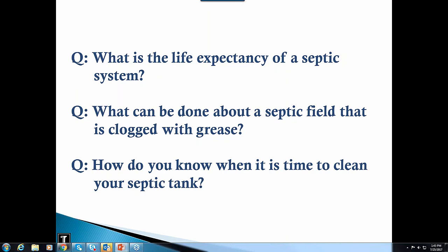That sounds a lot cheaper than redoing your septic field. It is, but maintenance is key because it's going to have to be cleaned more often than your septic system is going to be pumped. So at least once a year, maybe even every 6 months, depending on use, you have to get in there and get that T out. But it rarely comes out. You spray it with a garden hose to take off any of the solids that are built up there, and you just insert it back in. But it's just an extra measure to make sure that any solids or any grease don't make it out of your septic tank.